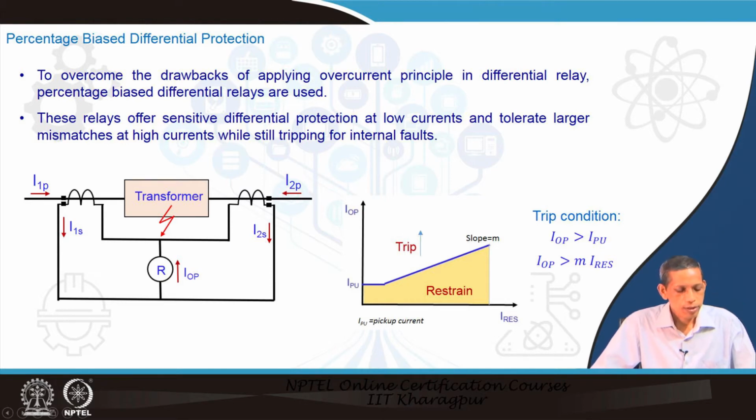So, what is being done here? For these kinds of connections, we have the relay characteristic, a very basic one that we are going for, and then we will go for further details on this: the differential current versus the corresponding restraining current. Agree? This restraining current is related to the through current, and the corresponding operating current will be more and more.